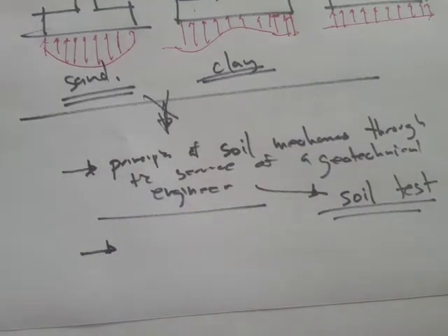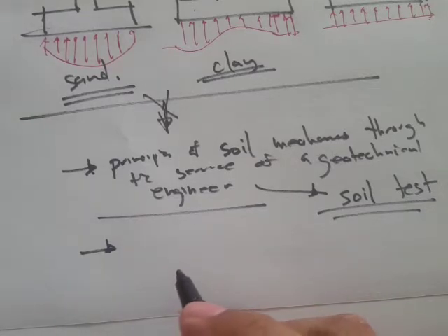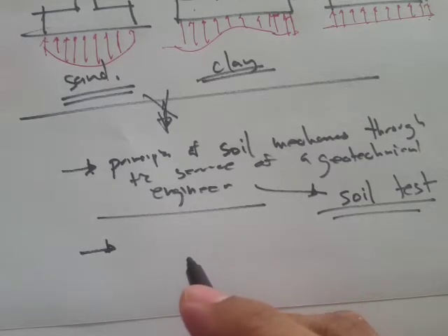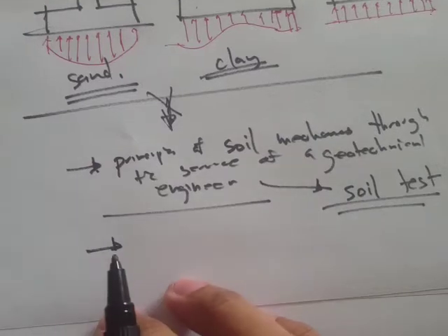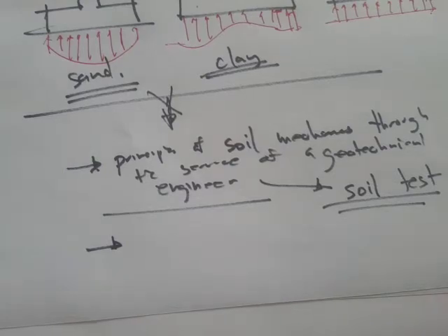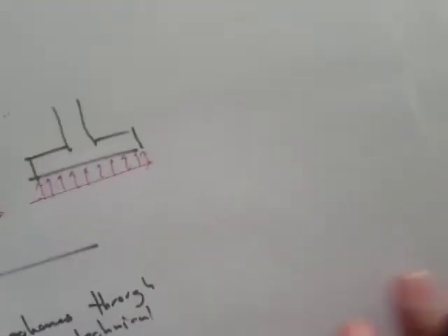Now, in the absence of this geotechnical report or soil test, there's also data provided in the NSCP and, I think, in the National Building Code, which specifies the different types of soils and the allowable or permissible bearing capacities or pressures at a given minimum depth. It's also included in our lecture handouts, and we'll just discuss some of them here.